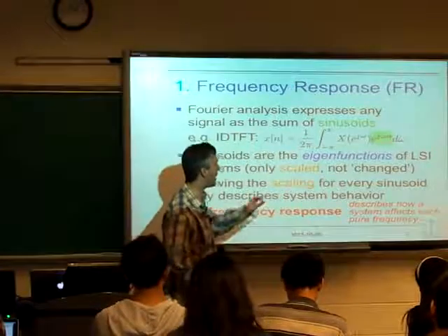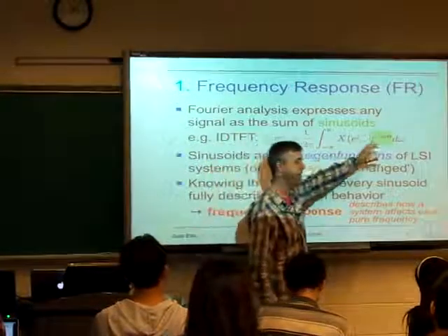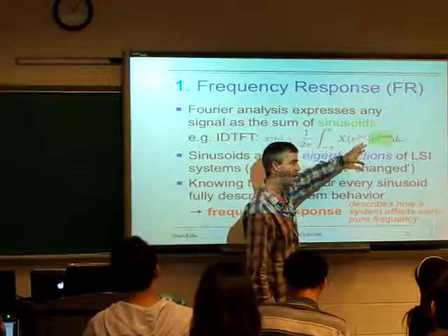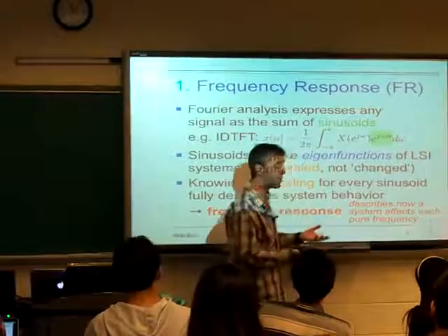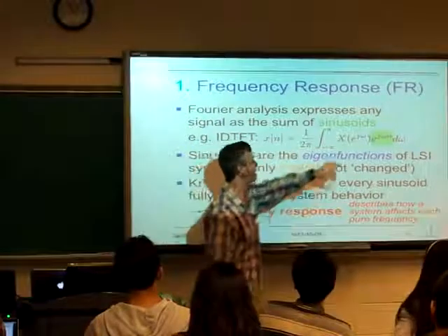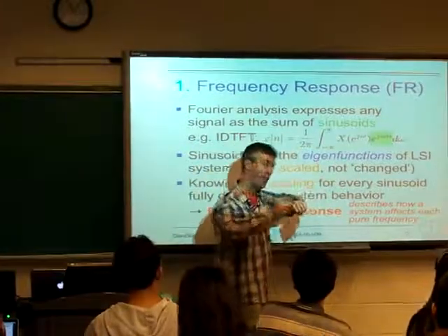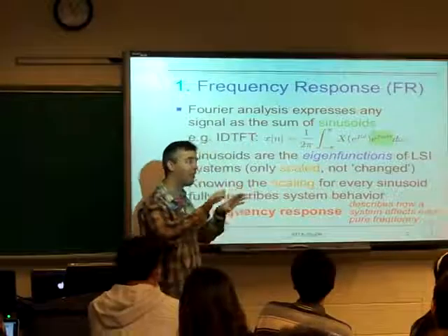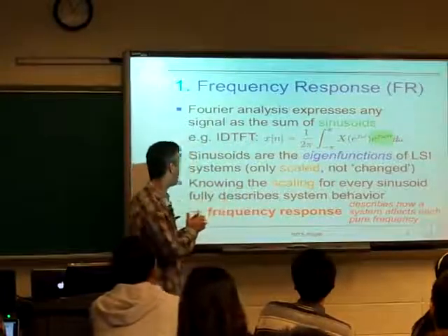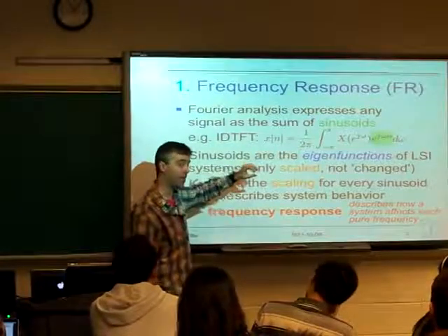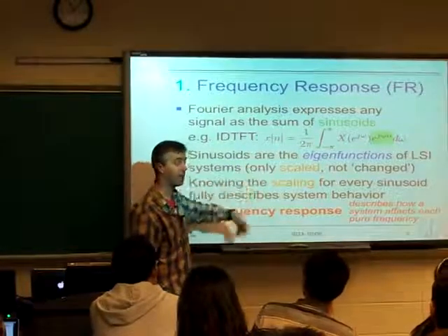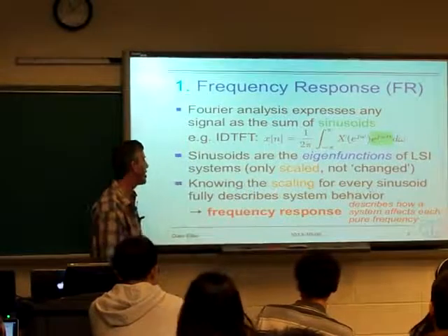And that's this idea of eigenfunctions: if you have a signal which is a sum of individual sinusoids, then the output of putting it through this transformation is that each of the eigenfunctions is just scaled. We're only going to get the ones out that we put in. And this is because these sinusoids are the eigenfunctions of linear shift invariant systems, the systems that we can characterize by their Fourier transform.